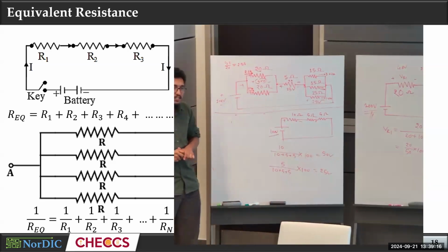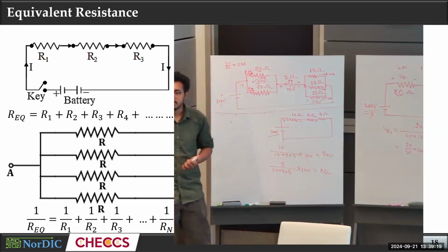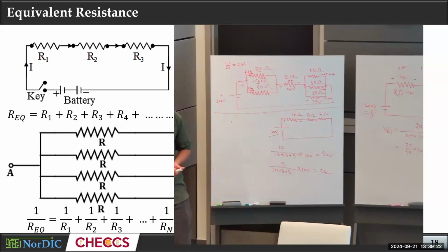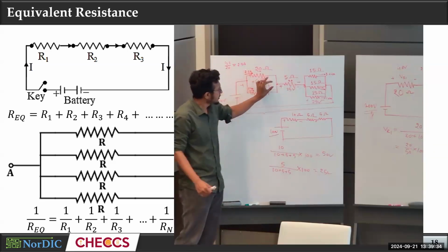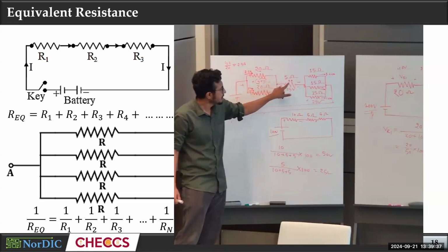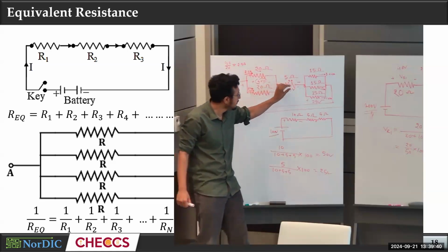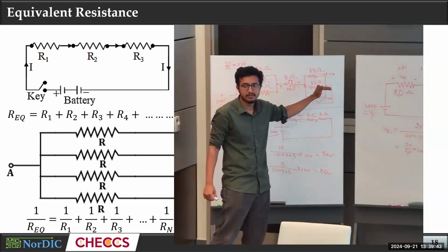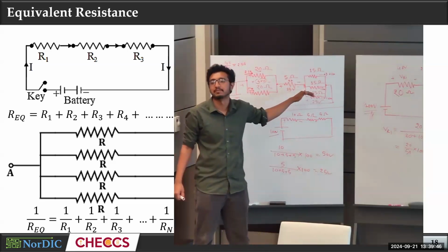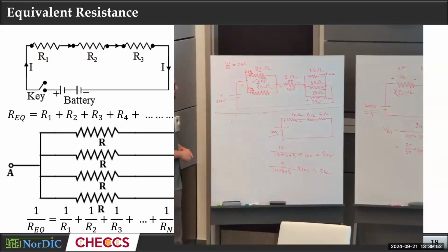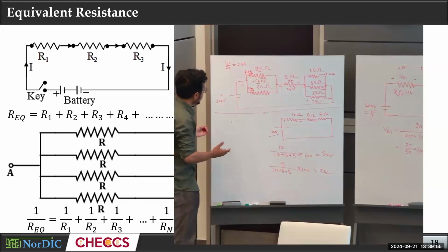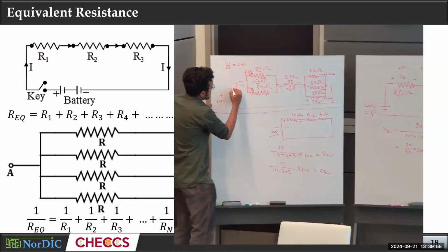So we get the voltage and currents across each of the resistors easily. Does anyone have any confusion? Now, 2.5 amps and 2.5 amps are added up here and become 5 amps. This 5 amps is dividing again into 1.67, 1.67, 1.67. You sum this up, you will get 5 amps. You see, current is being divided among the resistors. Now, let me tell you what is the current here. What is this?